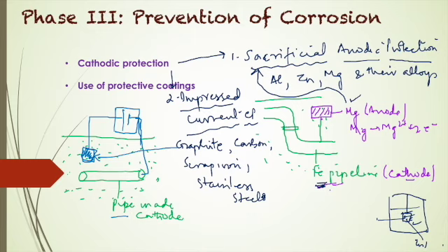Okay. How do they function? They are more inert organic barriers, and their protective value depends on the chemical inertness to the corrosive environment. It has a good surface adhesion, its proper application method, and the protective value also depends on impermeability because of its impermeability to the gases, salts and water. So these are the stories of metal and organic coatings for prevention of corrosion.